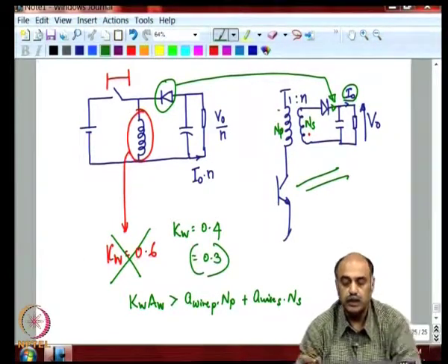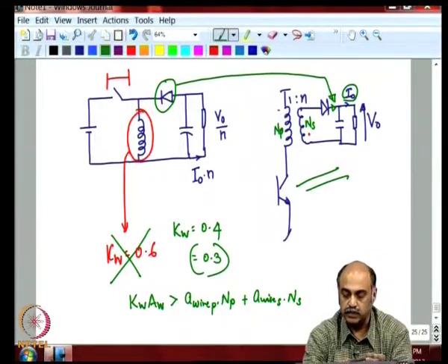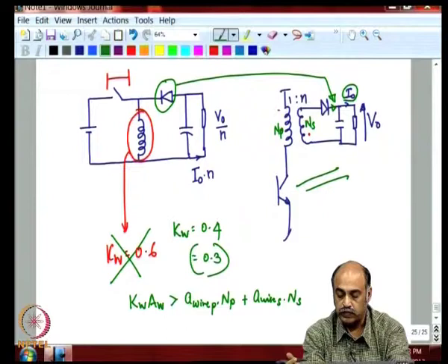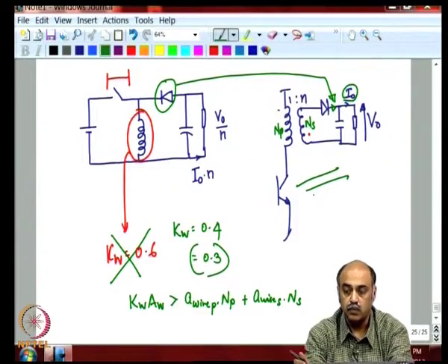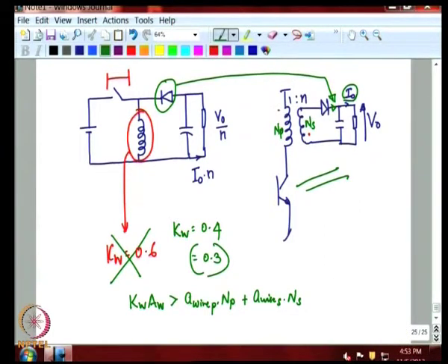Flyback is very popular, and even though the quality of the output is not as good as a forward converter because there is no output filter inductor, the flyback converter is very popular basically because of its very low component count. You see that there is only this diode, the capacitance, one inductor cum transformer, isolator, and the power switch. So, this gives a very cost effective design, even though one needs to sacrifice to some extent on the quality of the output voltage.